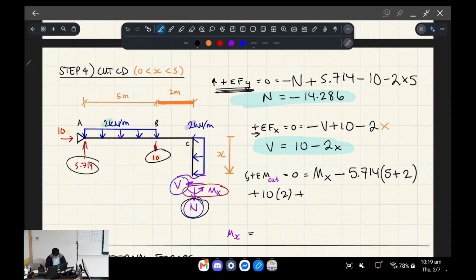And then let's consider the equivalent point load for that distributed load. And just like before, we have a fixed magnitude of 2 meters multiplied by 5 meters. Okay, so that's the magnitude. Sorry, I'm covering that plus sign. That's the magnitude of that distributed load. And now we also have a fixed distance. Okay, so the distance is going to be 2.5 plus 2.